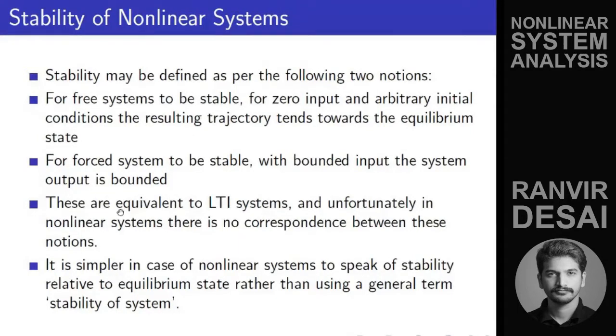These are equivalent in an LTI system, and unfortunately in nonlinear systems there is no correspondence between these notions. So it could be that a system is stable for an arbitrary initial condition, but it is not stable for a particular input, or vice versa. So they are unrelated in the case of nonlinear systems. It is simpler in nonlinear systems to speak of stability relative to an equilibrium state rather than using the term stability of the system.